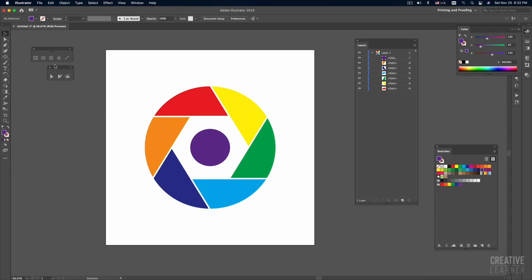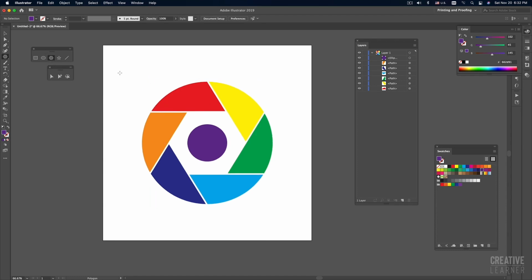Just now I showed you that in Illustrator we have this Polygon Tool. With the Polygon Tool, when we click and drag, that will be a hexagon, having 6 sides. But we need 5 sides for a pentagon. So before I click and drag, I just click once on my drawing board, anywhere, with the polygon tool selected. Just one click, and the polygon tool settings will appear.